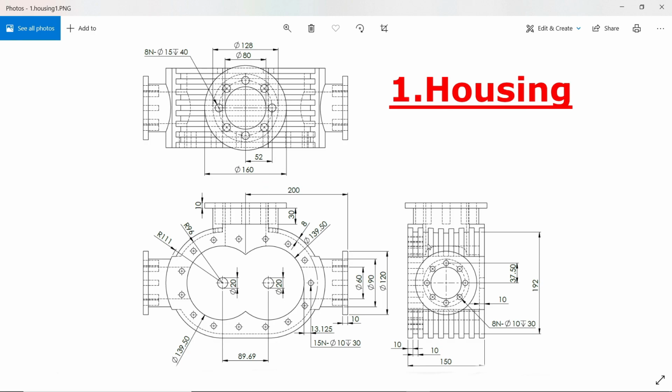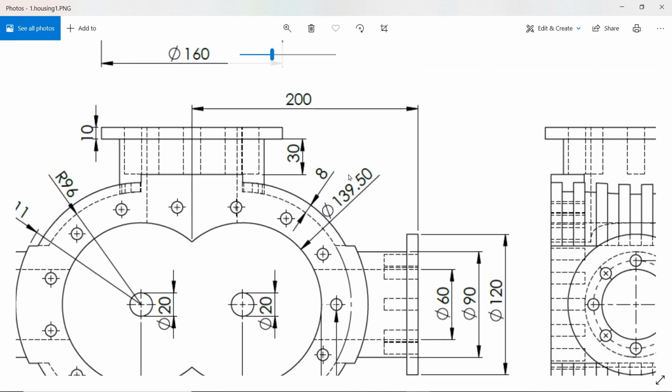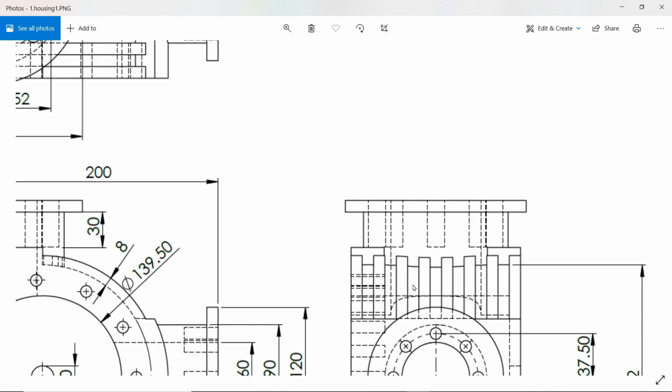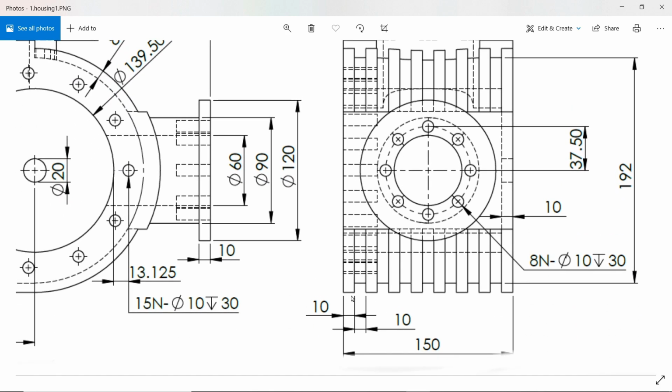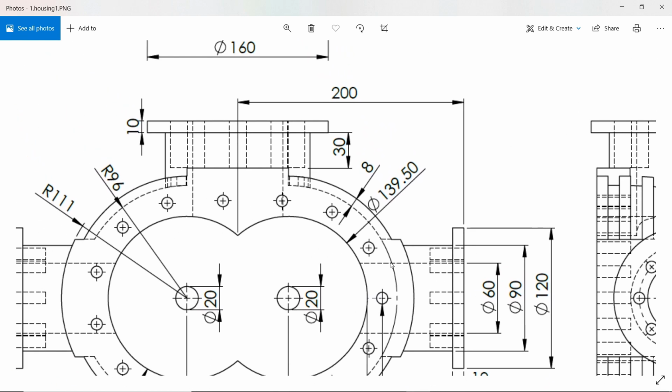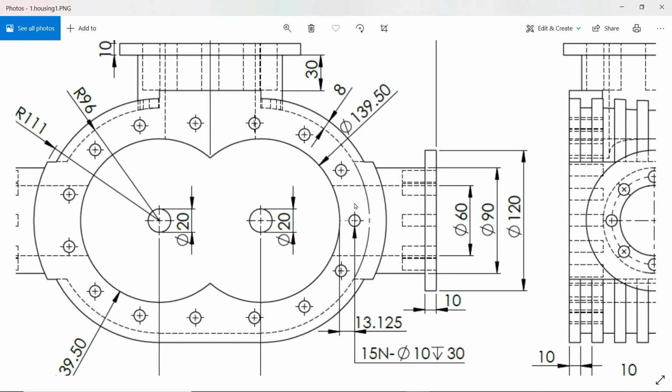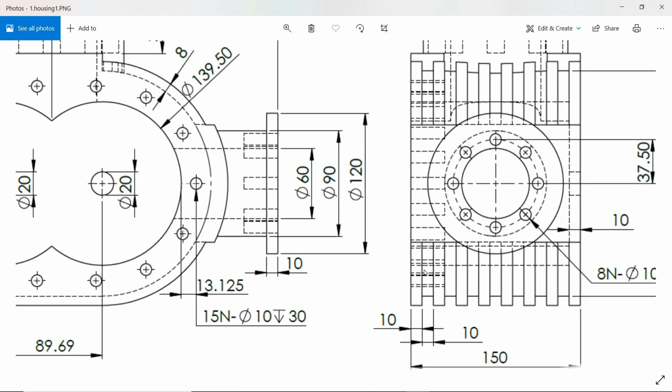Here next thing we need to create is these fins. There are 8 number of fins. You will see at bottom a 10 mm fin, and there is a gap also of 10 mm. And the distance of the fin is, see, 8 millimeter from the inside one. So we will create this one 10 millimeter, then we will use a linear pattern to create the rest.